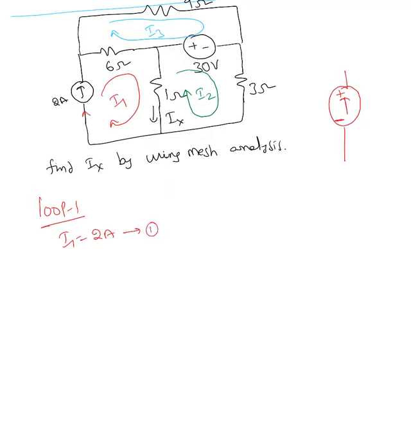That's our first equation. Now loop 2, do we need to apply KVL? Yes, because there is no current source in the outer branches. Okay, loop 2, apply KVL. Before applying KVL, you need to assign positive and negative signs according to your current direction. So I'm going to start walking from here. That's a voltage source. For a voltage source or current source, you don't need to assign any positive or negative signs. So that's positive, negative, positive, negative.